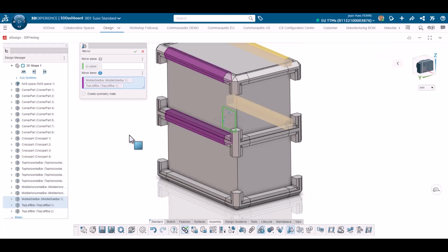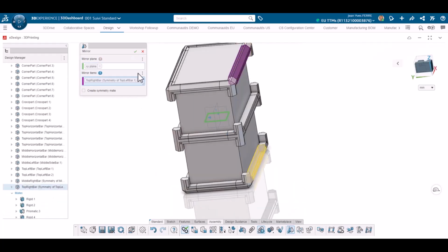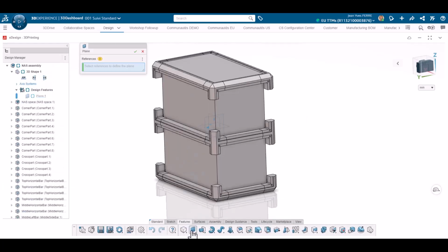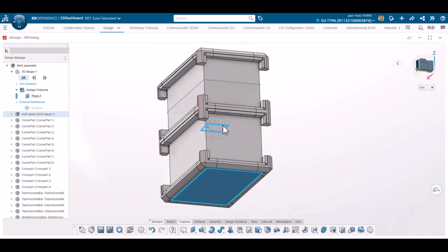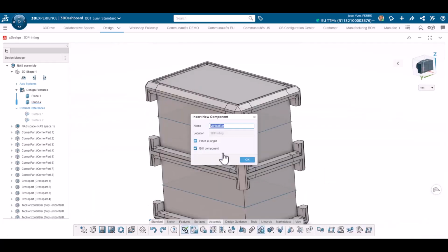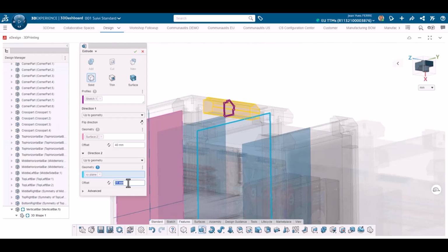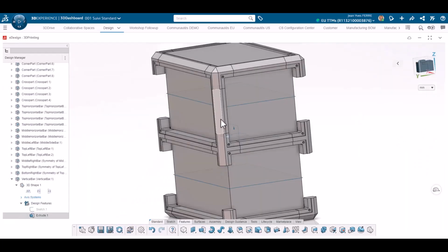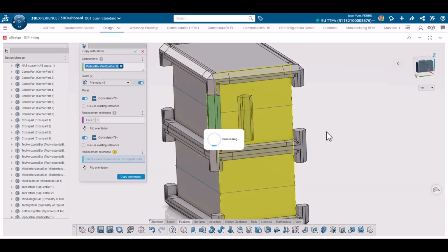As I anticipate some changes, I create a mirror for the top bar so there will be 2 separate objects. You will see why in the episode about motherboard positioning. Only vertical bars are missing, but because everything is symmetrical, I just need to create 1 bar. I start with positioning planes in the middle of each section. And as I did before, I create the bar with the sketch taken from the corner part and an extrusion up to each part to adapt for changes.